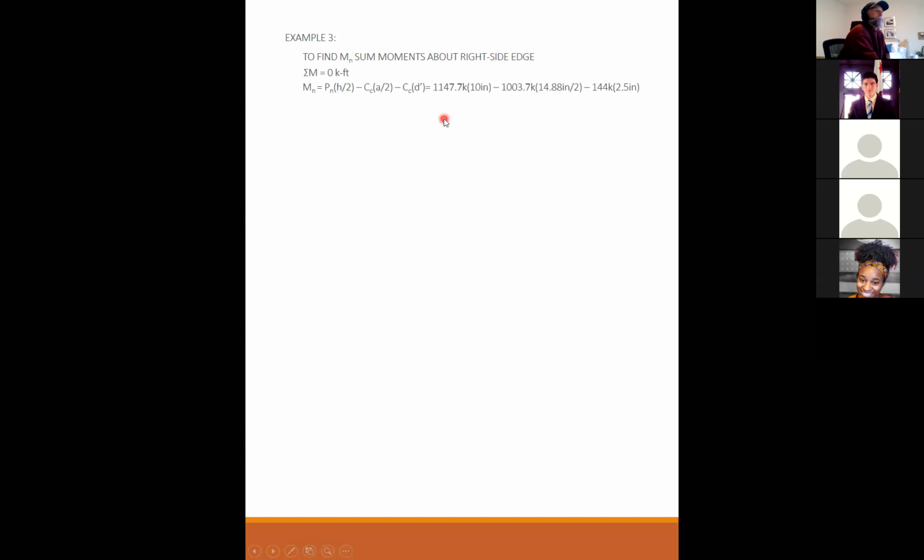Anyway, the axial load times half of the column plus the compression in the concrete times a over 2 plus the compression in the steel times d prime gives 3,649 kip-inches, 304.1 kip-feet. Since epsilon t is equal to 0, phi is 0.65. Phi Pn is 0.65 Pn, which is 746 kips. Phi Mn is 0.65 Mn, which is 198 kip-feet.